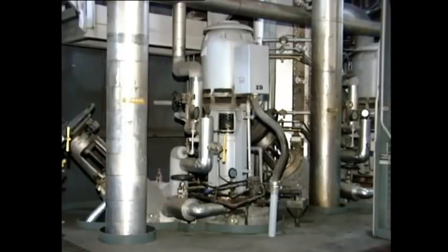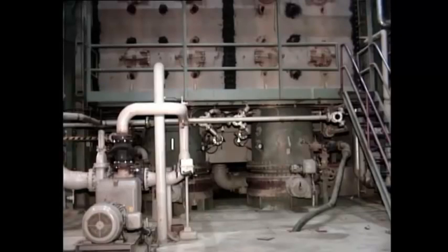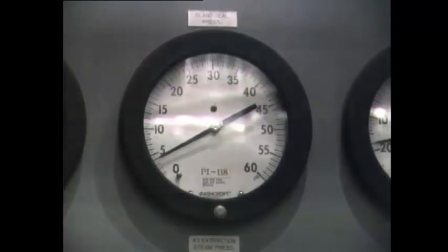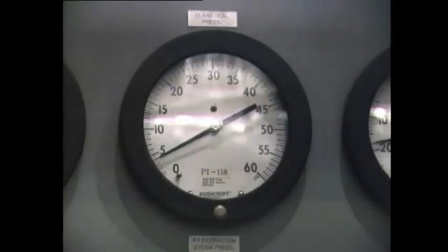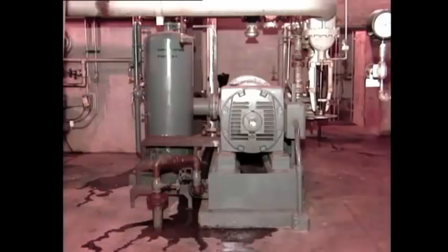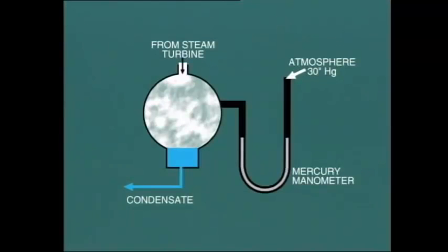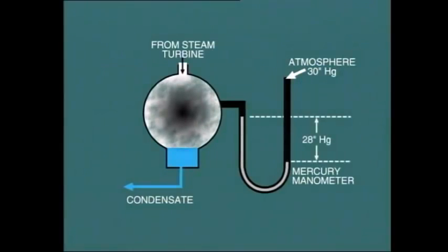During this period of time, the circulating water system should be started up and the flow of water established through the condenser. We can also begin to draw a vacuum in the condenser by extracting all of the air. Before beginning this activity, it will be necessary to put the gland steam system into operation to prevent air from entering the turbine at the shaft seals. The vacuum pumps or startup ejector are placed in service, and we can observe the indicated decrease in back pressure from atmospheric, about 30 inches of mercury, down to, say, 2 or 3 inches.